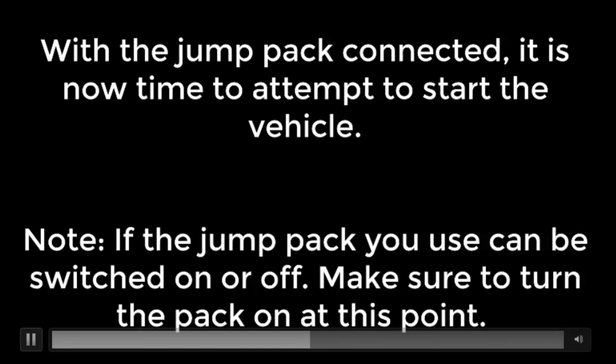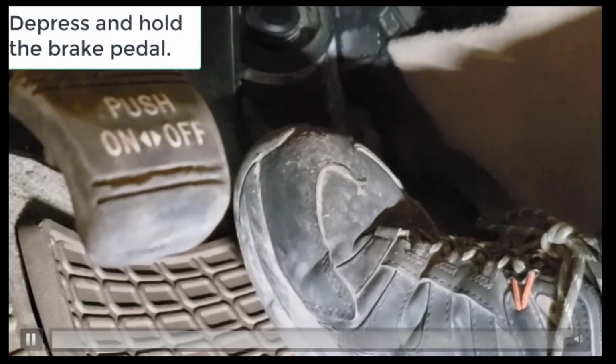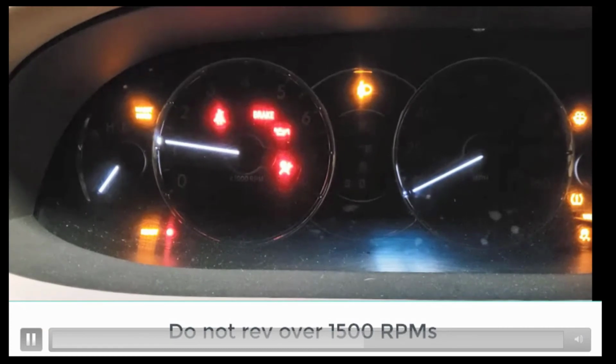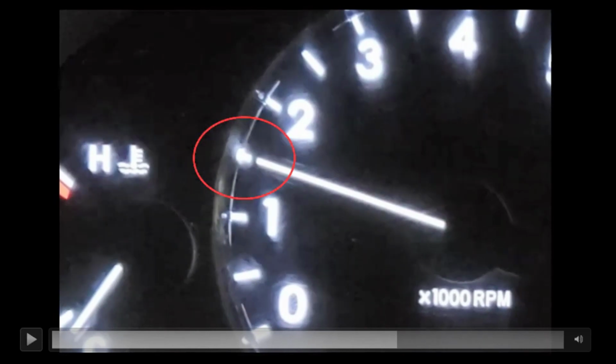So with the jump pack connected, now it's time to start the vehicle. If you have a switched kind, you'd switch it on. Now you want to make sure that you're stepping on the brake pedal when you do this. If it has a manual transmission, you also want to make sure you're stepping on the clutch. You're going to press the button or turn the key to start the engine. Don't rev over 1500 RPMs. Typically, a vehicle in open loop will obviously hit the 1500. I know Toyotas will, very common. Don't go any more than that.